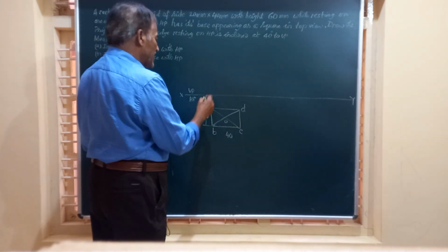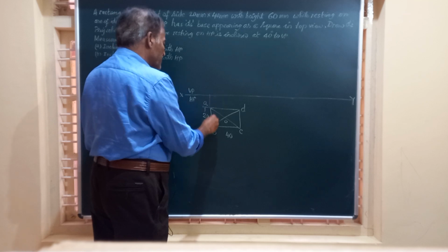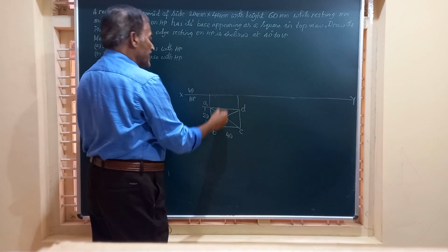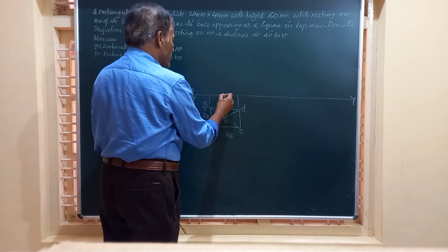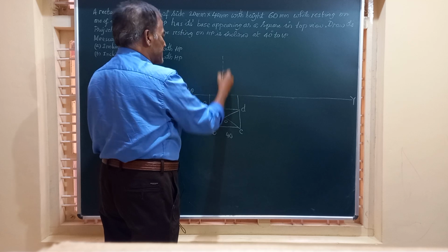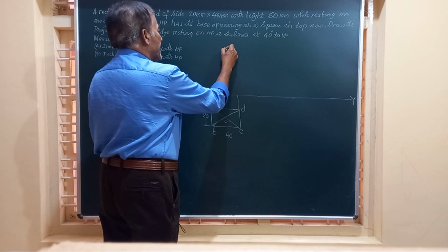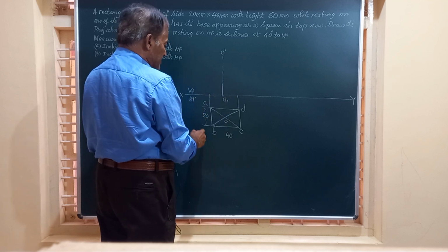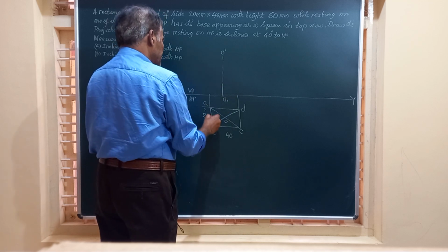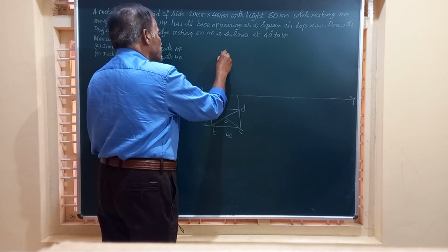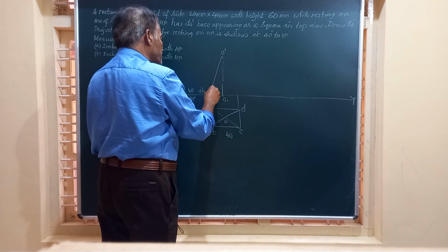So friends, we will transfer all these to the front view and obtain the front view to the given height of 60 mm. So from the center, I am going to mark a vertical line representing the axis, that is O dash, O1 dash. Join all these points, like A dash B dash, to be joined to O dash.